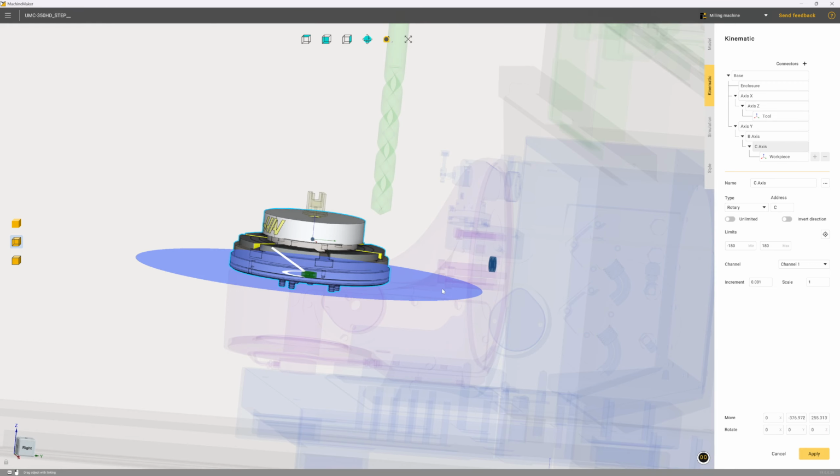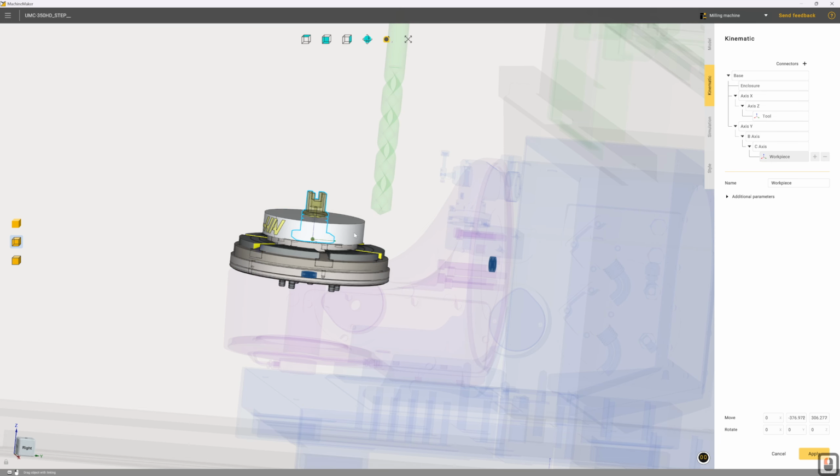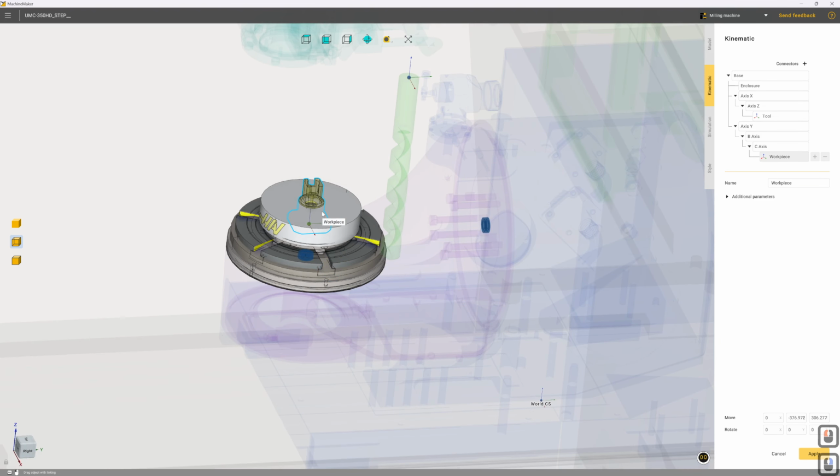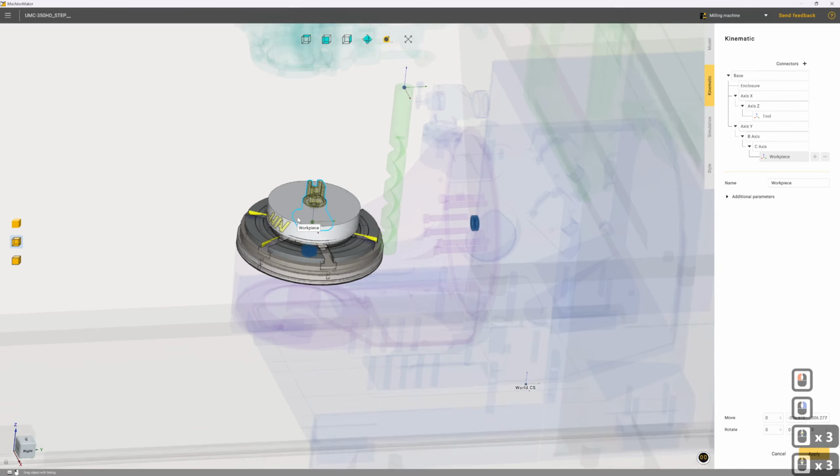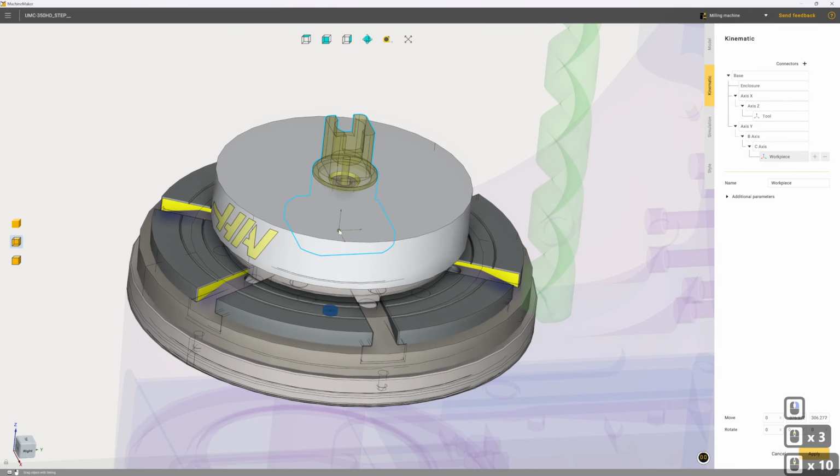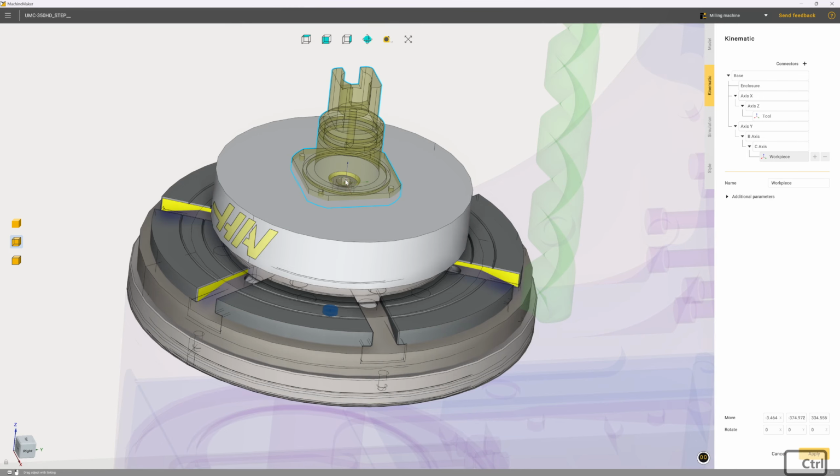That's absolutely fine. The next thing that we're going to do is move the workpiece attachment point, because that needs to be further up and again remain centered. So let's zoom in, hold down Control to move it, and once again, we're relying on the snapping here. We can see the nice orange ring there, which means it's snapped to the center of that circular edge.